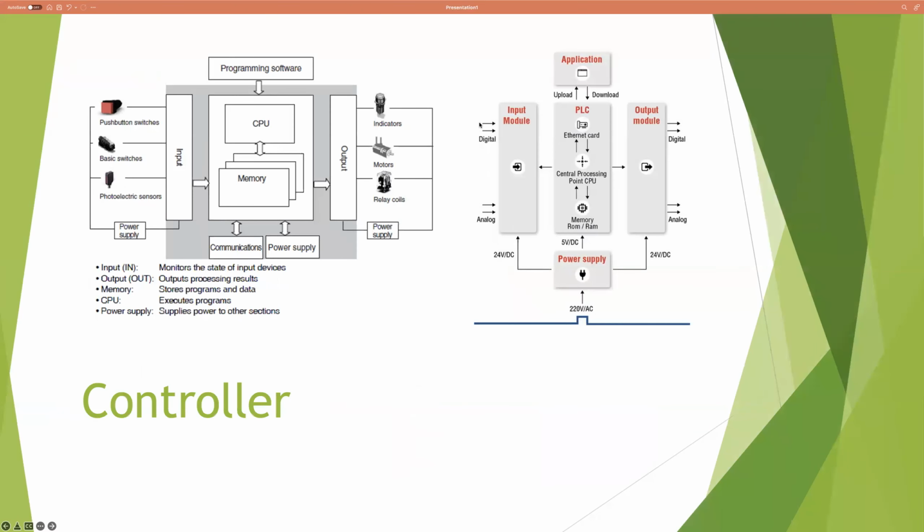And obviously the PLC: we're going to need a controller to read these signals from the push buttons or from the sensors, because the curtain is going to work on a button type of operation. Automatic: you press a button. Manual: you keep pressing the button, and it's going to send an output to the motors.